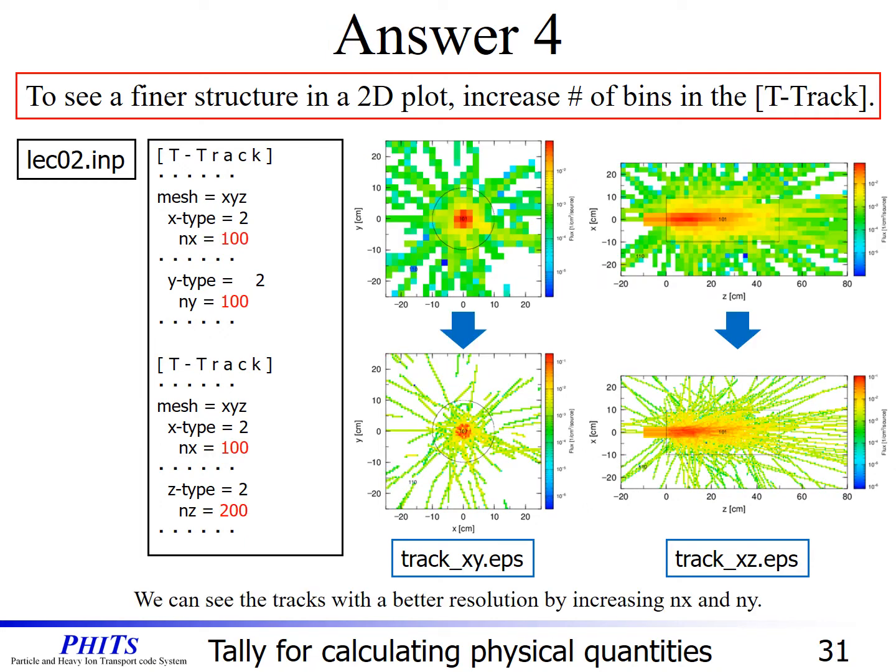We can see the tracks with a better resolution by increasing the number of mesh. It should be noted that the file size becomes large when you increase the number of mesh. So please set the appropriate number of mesh for your purpose.